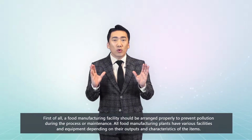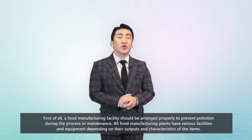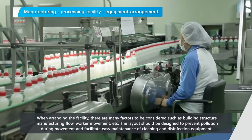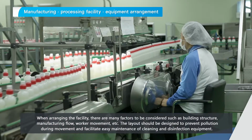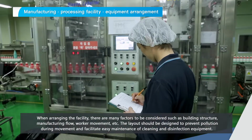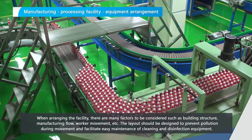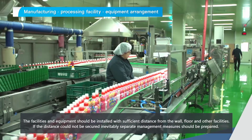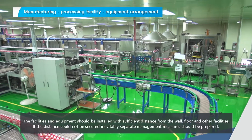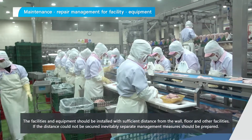All food manufacturing plants have various facilities and equipment, depending on their outputs and characteristics of the items. When arranging the facility, there are many factors to be considered, such as building structure, manufacturing flow, worker movement, etc. The layout should be designed to prevent pollution during movement and facilitate easy maintenance of cleaning and disinfection equipment. The facilities and equipment should be installed with sufficient distance from the wall, floor, and other facilities. If the distance cannot be secured inevitably, separate management measures should be prepared.